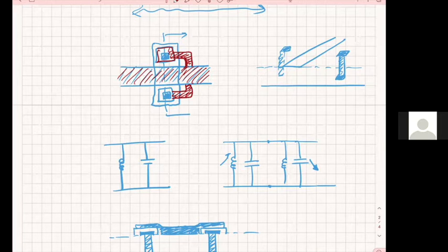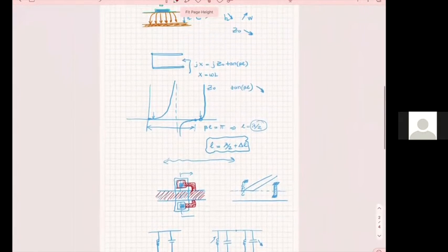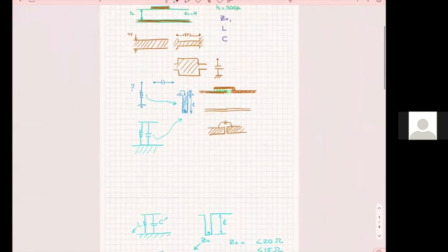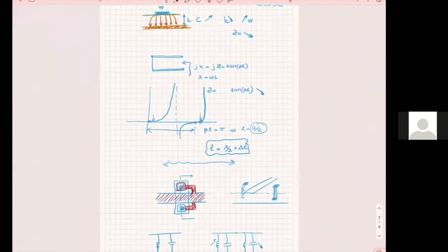All right? Exactly. For stubs, and that's what you go for first, all right? You go for a stub because that's the easiest one to do. But when you find that the values you get in your capacitance are unreasonable, then you look at something different. And that's why I try to explain what kind of thought process would take me down to saying, oh, well, this L is so small and it's shunt, this C is so high and it's shunt, I'll make them as lumped elements. And then you move on, okay?